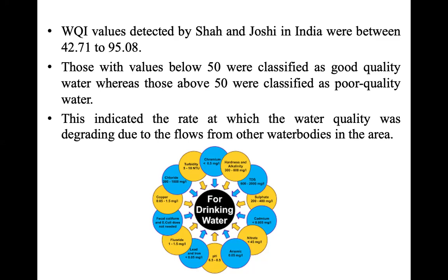So in water quality analysis, you are interested in finding out the pH of the water to ascertain whether it falls within a given acceptable parameter. You also look at the turbidity. Then you look at the total dissolved solids, otherwise known as the TDS, which must conform to values as you can see here.